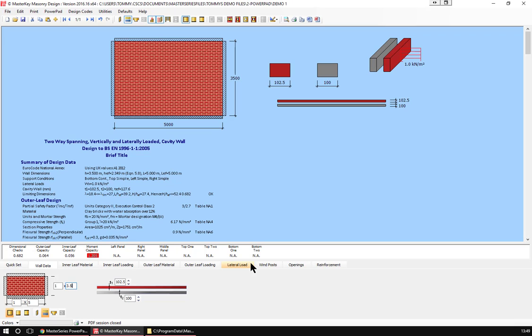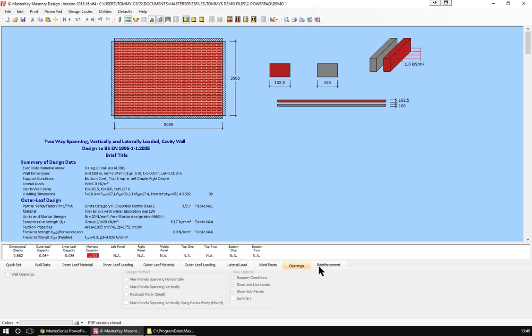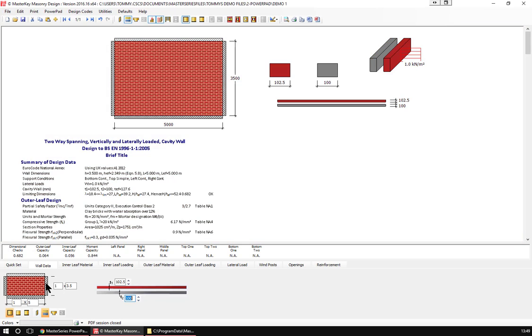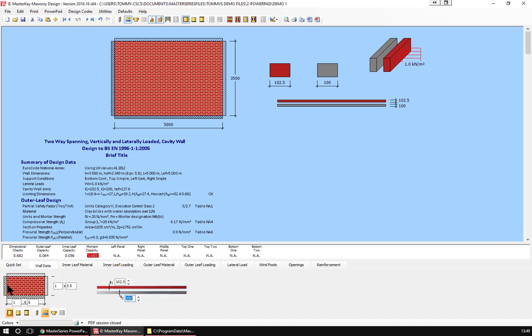Now, again, if we were in the full version, we would have access to openings, which are no use to us here, but rebar in the beds. We don't have bed joint reinforcement. So all we can do is either turn around and say, well, actually, it's a bit better. It's actually fixed on the two sides. Fixed on one side is not good enough. It's something that we used to do when I was a practicing engineer, to say, well, at least every other one was fixed, because you would have the continuity every other at least. That's not working. So what do I have?